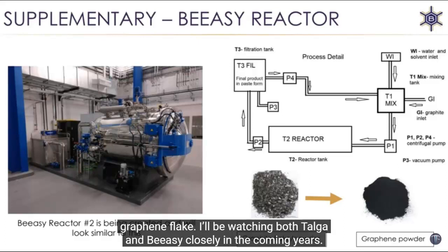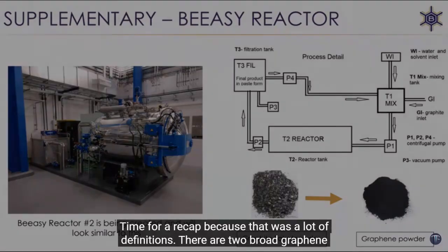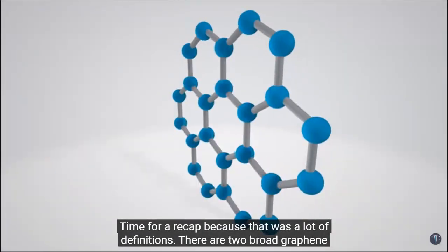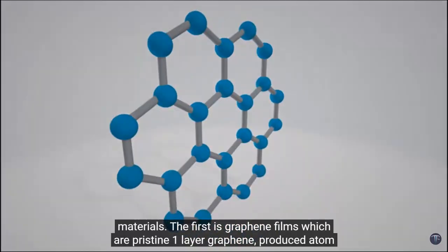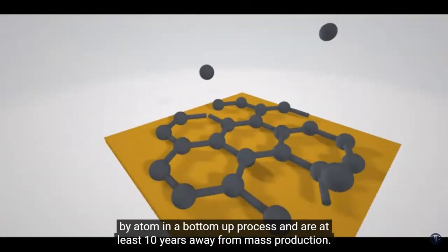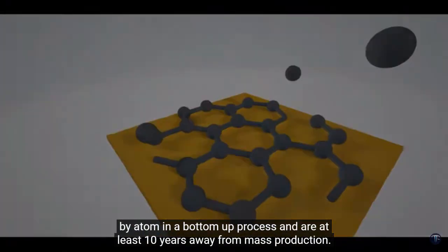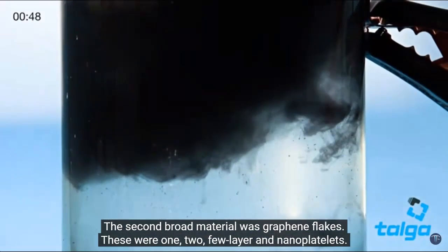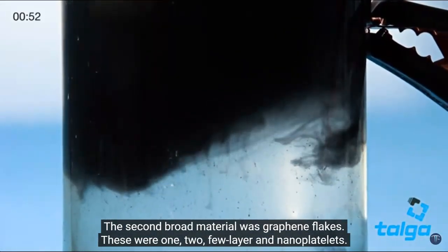Time for a recap, because that was a lot of definitions. There are two broad graphene materials. The first is graphene films, which are pristine one-layer graphene, produced atom by atom in a bottom-up process and are at least 10 years away from mass production. The second broad material was graphene flakes. These were one, two, few-layer, and nanoplatelets. Graphene flake is produced with a top-down method, and some producers are already ramping production.